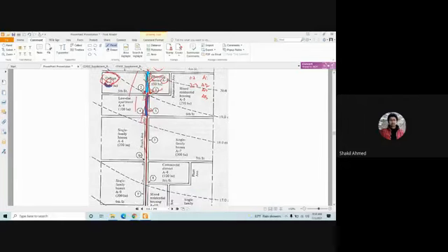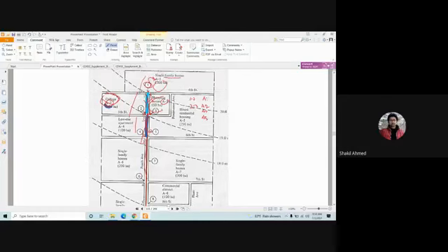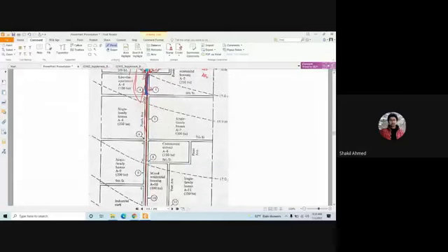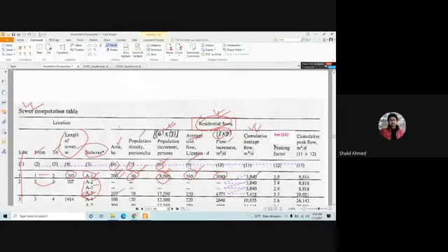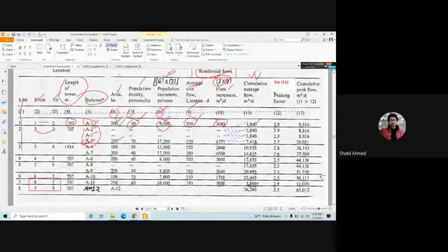So that means starting from here, all the wastewater is going to contribute in 3 to 4 and then 4 to 5 and so on. So that's why we have to take the cumulative average flow. 7415 plus 2640, 10,000 something. 10,000 something plus 4560, 14,000 something. Okay, clear. Yes, sir. Now, peaking factor.